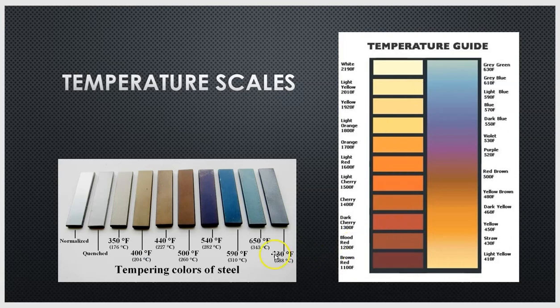So anything over 730 degrees, or we can even say 630, anything over that range, 630 to 730, that is less tempering, more normalizing. So we need to know the differences in temperatures in order to achieve the appropriate heat treatment. So tempering, use this scale. If we're using something like annealing, normalizing, or heck, even quenching, this could be a scale that we use right here.